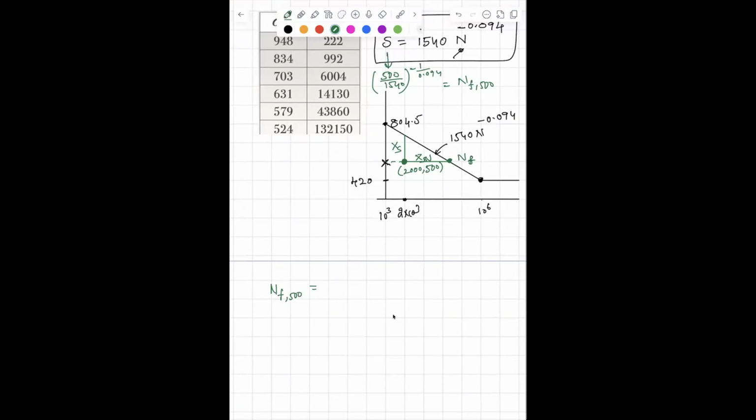Sir, one question actually, if I plug in 2 into 10 power 3 in the equation, I'm getting 753 as a stress actually. No. That is this value. 2 into 10 power 3 will tell you this. At 2 into 10 power 3, what is the value of that? Failure. Okay, got it. That is what I am calling sigma F. Yes, sir. This equation represents points on that line only. Your component is designed for that.